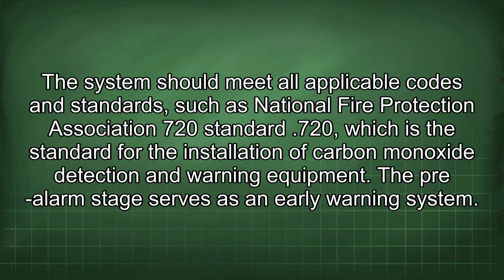The system should meet all applicable codes and standards, such as National Fire Protection Association Standard 720, which is the standard for the installation of carbon monoxide detection and warning equipment. The pre-alarm stage serves as an early warning system.